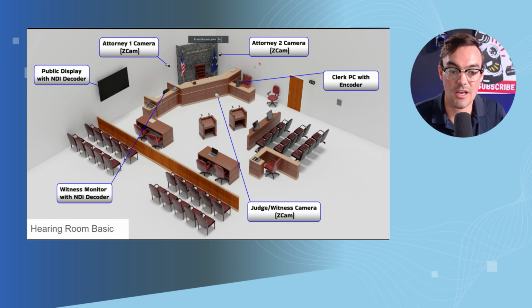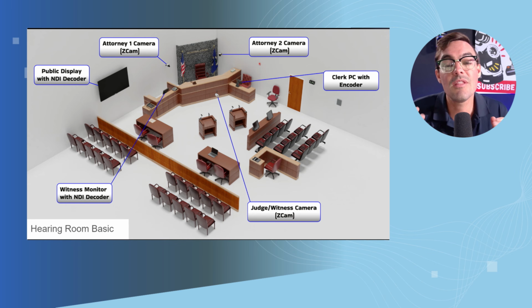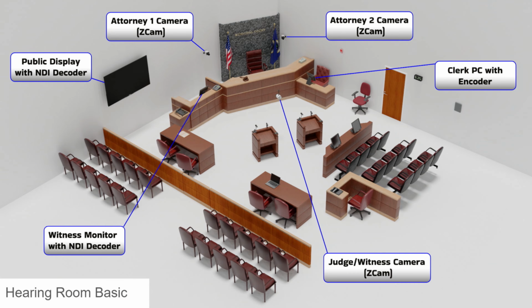Now, a lot of our customers, and we have some case studies on our website, like the New York court system, for example, are using NDI. And NDI is an IP video connection system, and they're leveraging networking switches. So network equipment can provide PoE networking power, power over Ethernet, to the devices, which allows you to remotely manage the devices, to control the devices, and to power them.